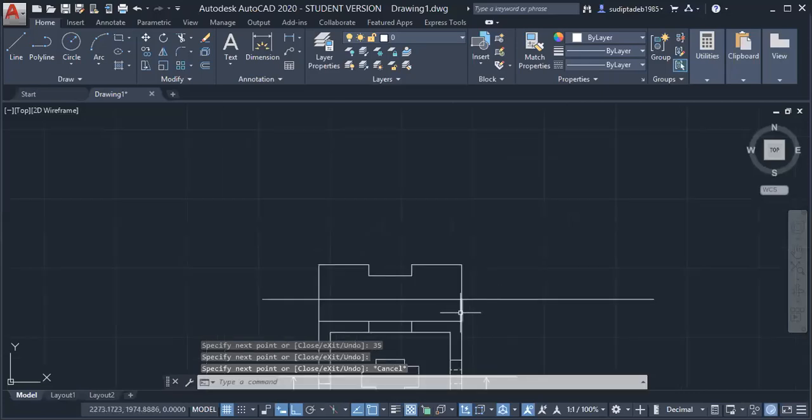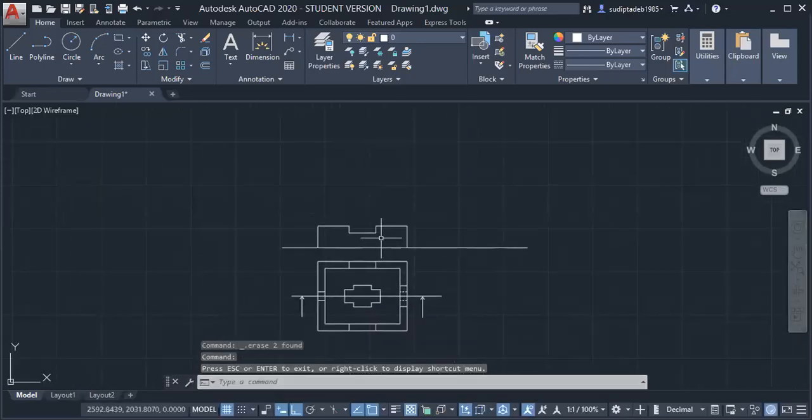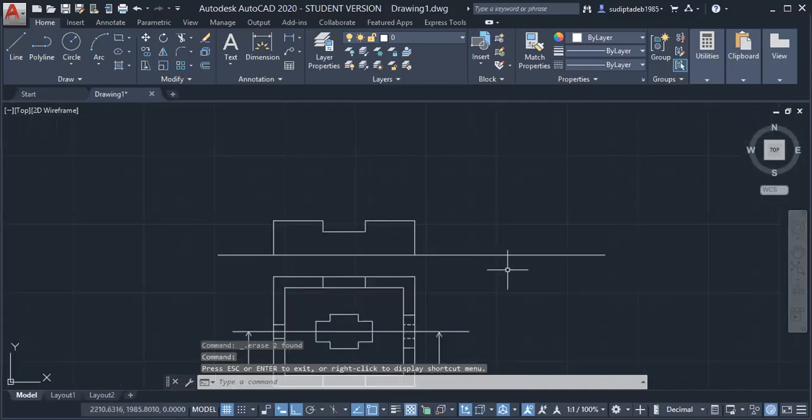I am drawing the lines. Just let me delete this portion, then you can understand actually what happened. I am drawing the object from the reference line because the object is lying on the HP. So from your front view, you cannot see any distance from the HP. That's because the object is lying on HP that I am showing here. But there is a gap in between VP, so that I'm showing on top view. Clear?